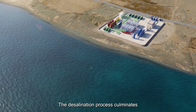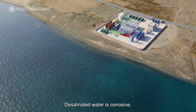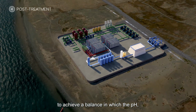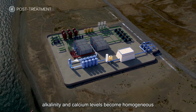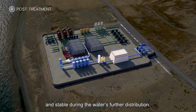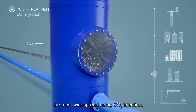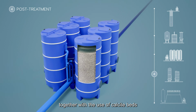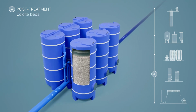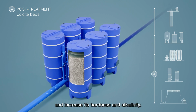The desalination process culminates with a post-treatment. Desalinated water is corrosive. It must therefore be remineralized to achieve a balance in which the pH, alkalinity and calcium levels become homogeneous and stable during the water's further distribution. There are several remineralization techniques, the most widespread being CO2 injection, together with the use of calcite beds that add calcium carbonate to the water. With them, it is possible to adjust the pH of the water and increase its hardness and alkalinity.